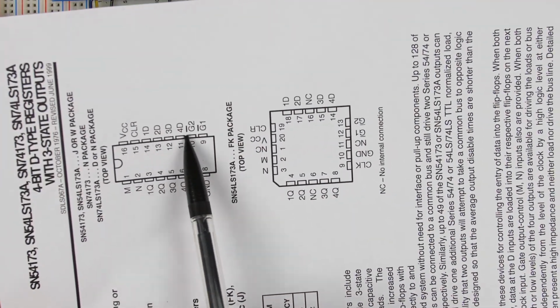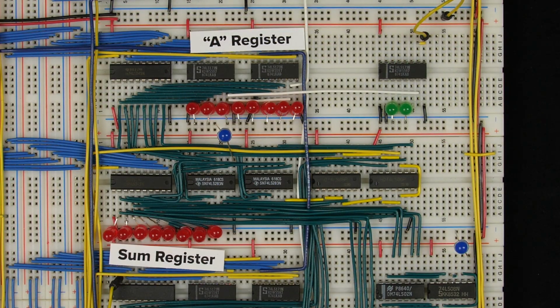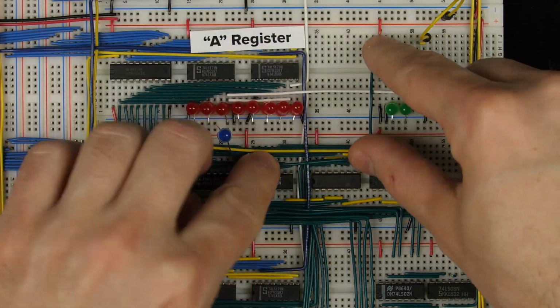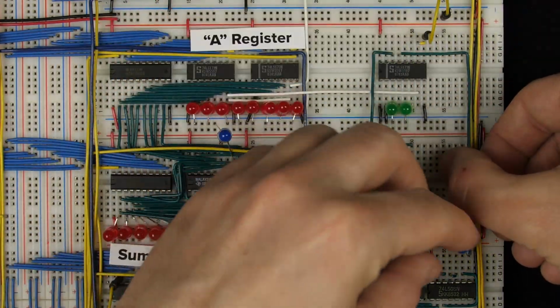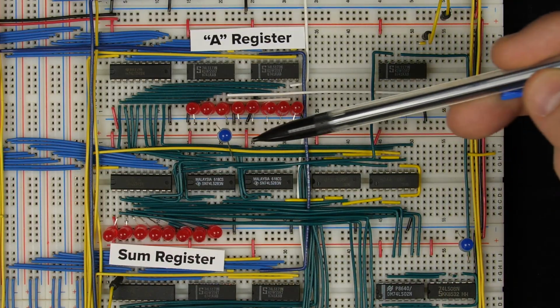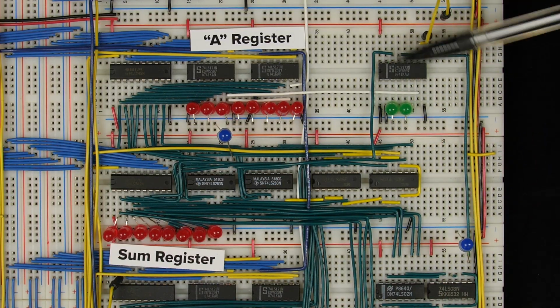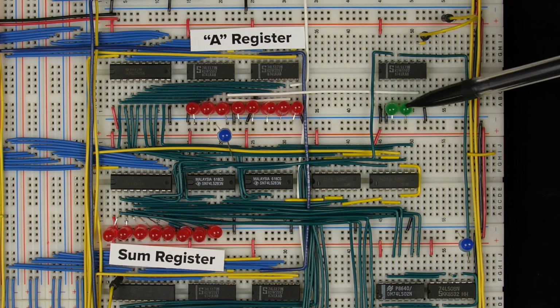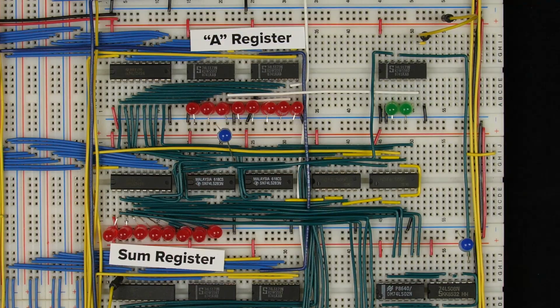And next we get to the inputs for our register, and these are pretty straightforward. We're just using 2 of them. One is going to come from the carry bit here. And the other is going to come from the 0 bit down here. So we've got our carry bit and our 0 bit going into the register here. And then when the register is enabled to latch in its input, it'll latch that in and store it here on the output of the register.